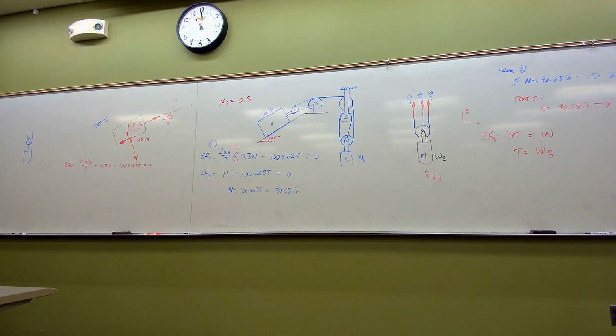Yeah, far away. So if you have one of the cables at an angle on there, would the weight still be evenly distributed across the cables? The tension would be, yeah, it would be. Because in that case, and to Nate's question, if we knew there was an angle, then you could say, well, there's a little X component, there's a little Y component, now when I add all the Ys together, it's gonna be slightly different. But it's so trivial, right? So we're not gonna worry about it. It's a good question. These are great questions, folks. I'm so glad you're asking these kinds of questions. This is good stuff. Anything else, anybody?